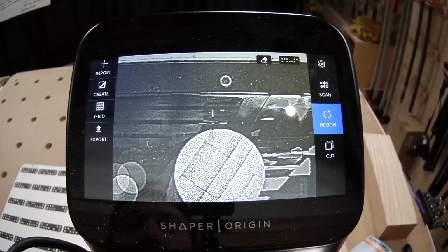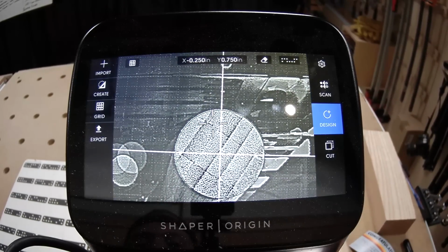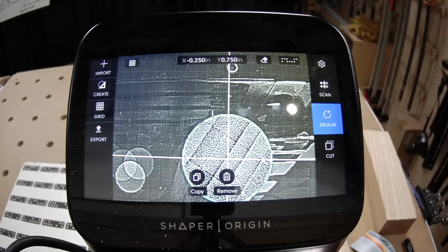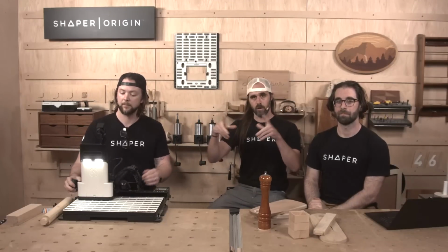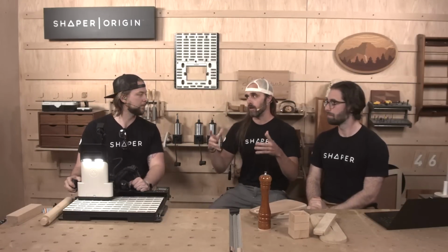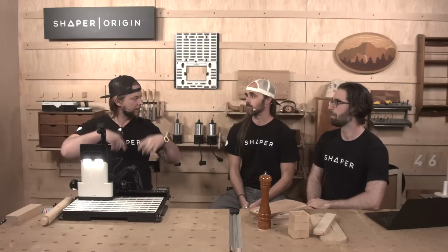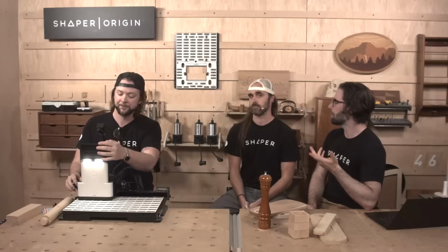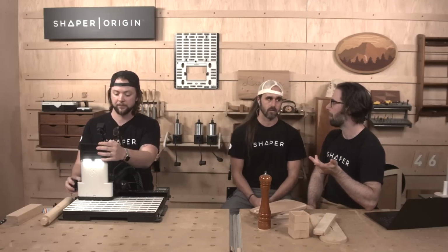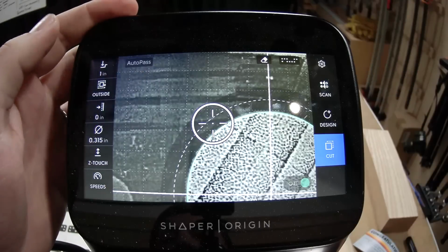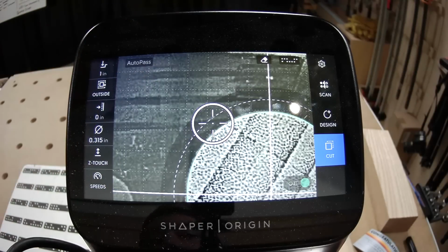and three. Yeah, and you'll notice when Jake's probing the circle, the further apart you can have the probes, the more accurate it'll be. If you put the probes right beside each other, you'll have a little less accuracy. So try to spread them out as best as you can to get the most accurate representation of that circle. Truly triangulating. Yeah, if you had a perfectly circular dowel, then this wouldn't be a problem. But when these wood dowels grow in one direction more than the other, that's where that inconsistency is going to come in.